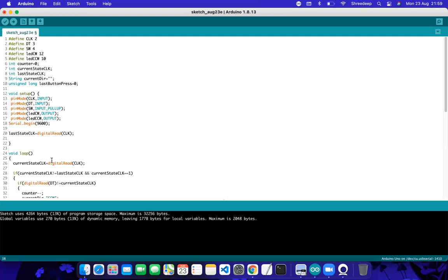But in case of an interrupt, what happens? You don't necessarily need to define the prototype of the function and call the function. You just write the function at your own convenient place, and the function would be called by itself when a certain condition is being met.